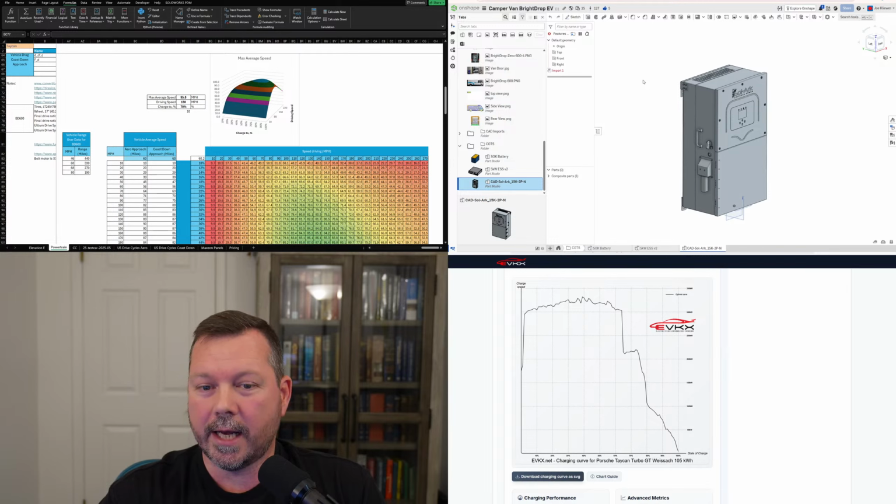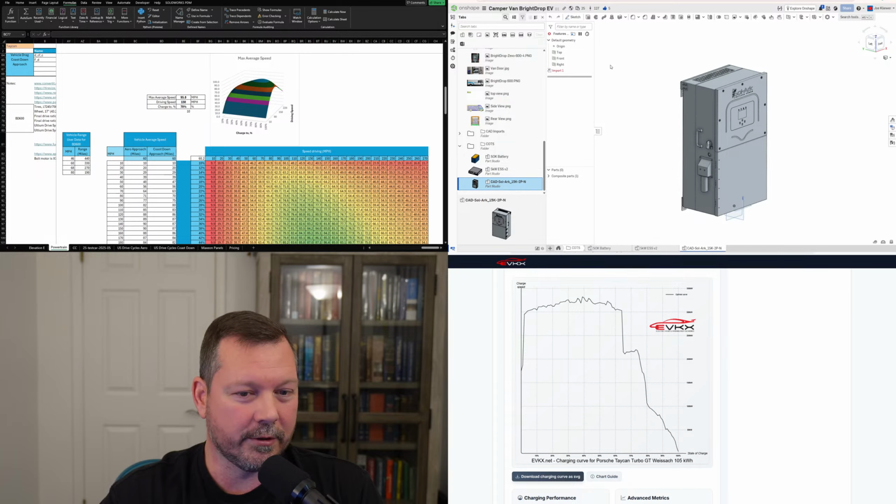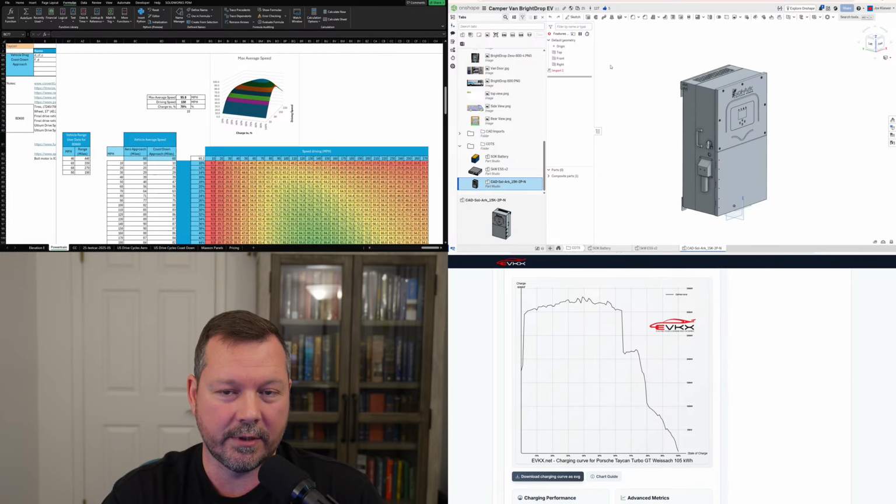Now, the ideal solution is you take the 2026 model year van, which I've heard there's a few of them out there. They're really hard to get. Maybe there's some more still stuck in Canada. And it has exportable power, so it has 7 kilowatt exportable, both 120 and split phase 240. So in that van, you don't need an inverter. All you need to do is charge the batteries.